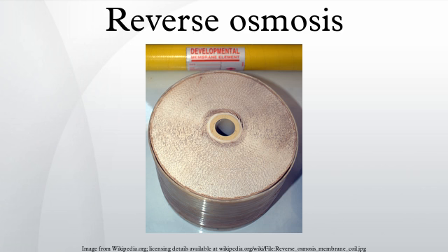New developments: pre-filtration of high-fouling waters with another, larger pore membrane with less hydraulic energy requirement, has been evaluated and sometimes used, since the 1970s. However, this means the water passes through two membranes and is often repressurized, requiring more energy inputs in the system, increasing the cost. Other recent development work has focused on integrating reverse osmosis with electrolysis to improve recovery of valuable deionized products or minimize concentrate volume requiring discharge or disposal. The latest developments when it comes to drinking water include nanoscale and graphene membranes. See also. References.